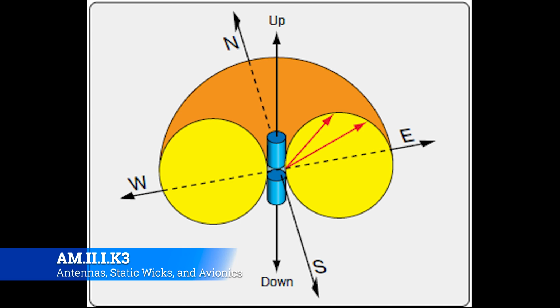As radio waves radiate out from the antenna, they propagate in a specific direction and in a specific pattern, and that's called the antenna field. The orientation of the electric and electromagnetic fields remains 90 degrees to each other, but they radiate from the antenna with varying strength in different directions. The strength of the radiated field varies depending on the type of the antenna and the angular proximity to it. All antennas, even omnidirectional ones, radiate a stronger signal in some directions compared to others, and this is known as the antenna field directivity.